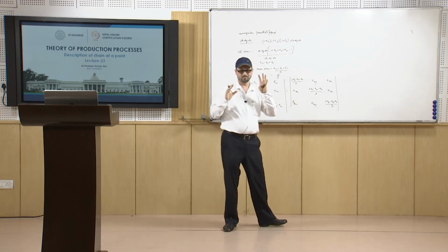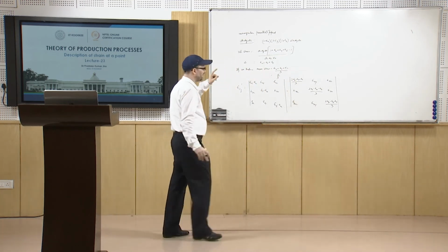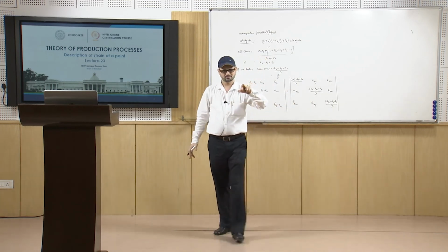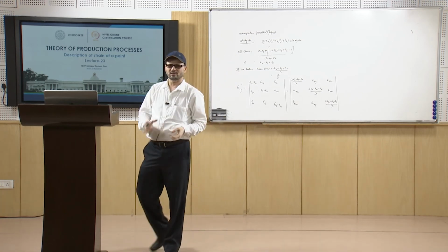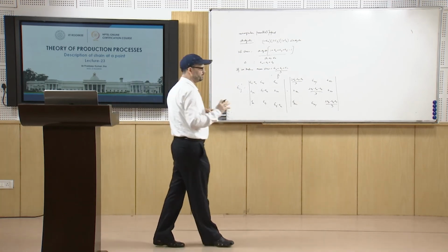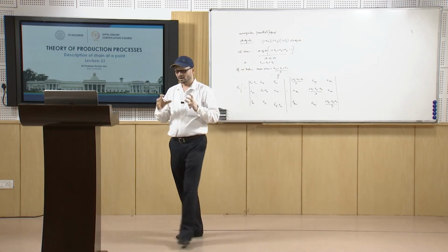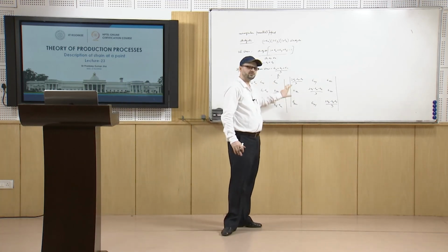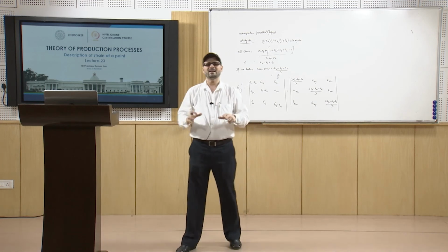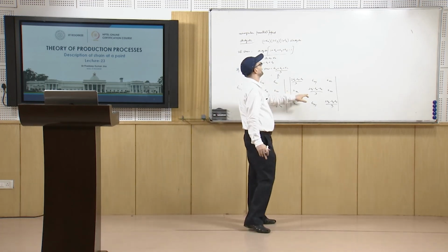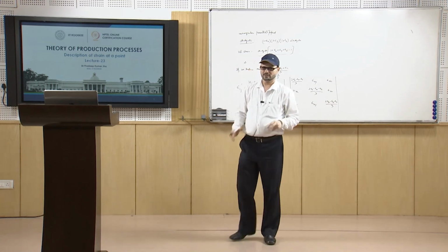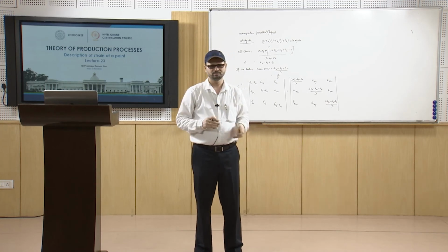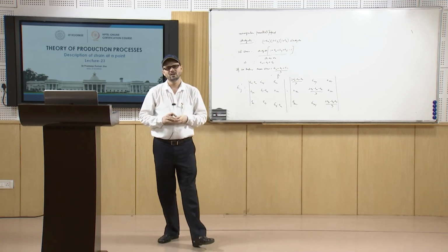One is the volumetric strain, that is the mean strain, and from the strain part you have removed that. The remainder is responsible for the shape change. The hydrostatic or mean component is responsible for any kind of volumetric change or volumetric strain, and the deviatoric strain part is responsible for the shape change.